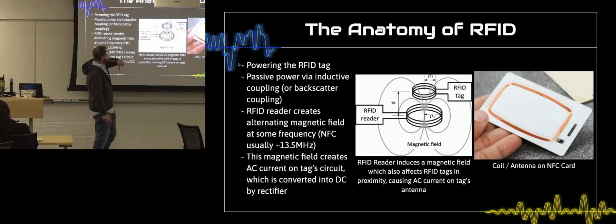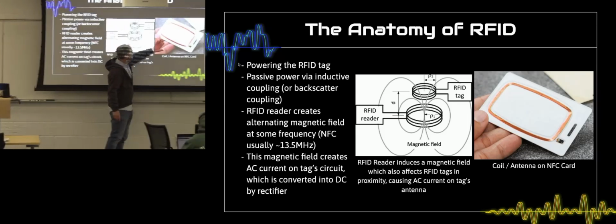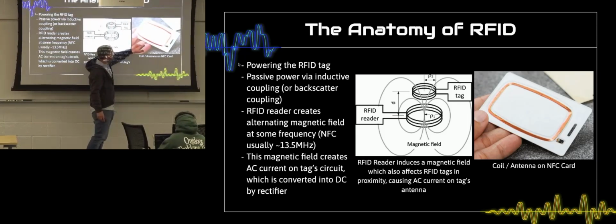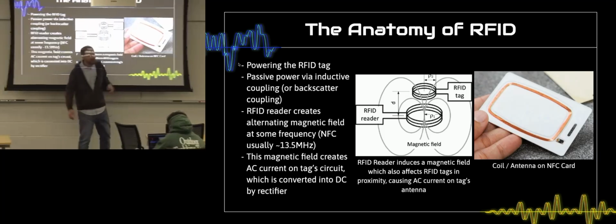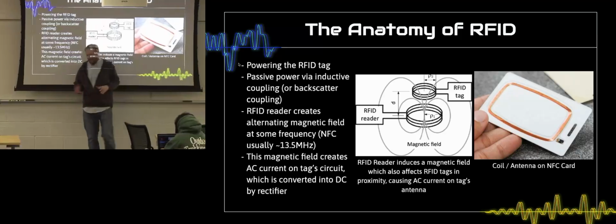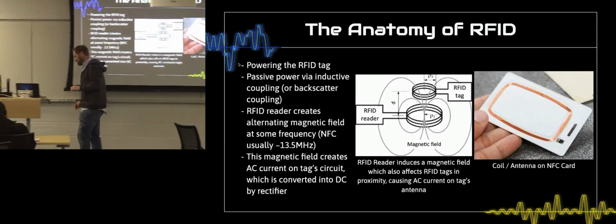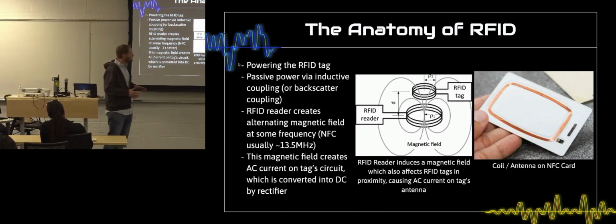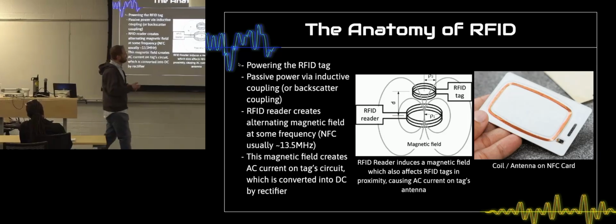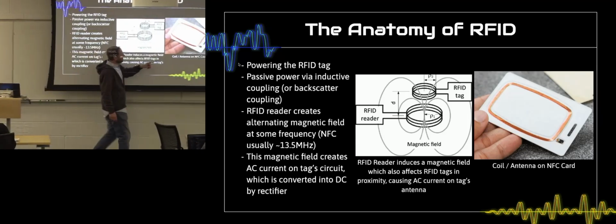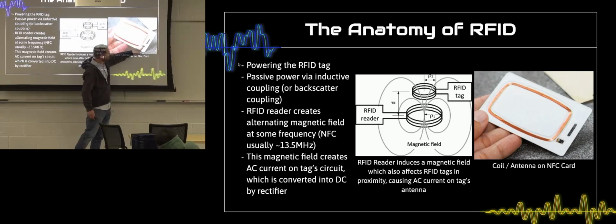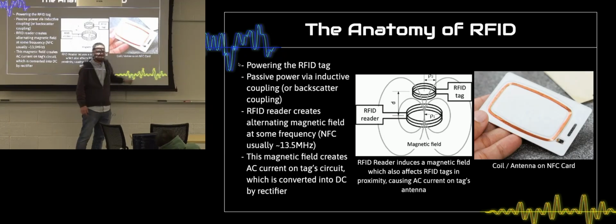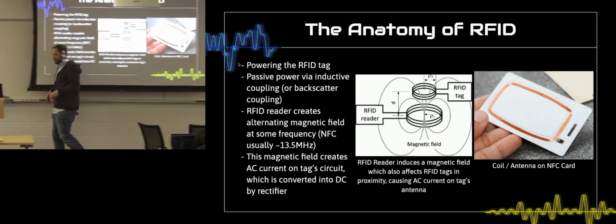They're specifically talking about this module, this type here. This is NFC, and there's a coil of wire here, and there's an IC here, and then the two are bonded. As a side note, RFID tags cost, I think the cheapest you could possibly buy in volume is about 25 cents or so, maybe 13 cents, depending on how big the IC is. And typically 1/3 is the cost of the coil, 1/3 is the cost of the chip, and 1/3 is just bonding them together, the assembly of those things.